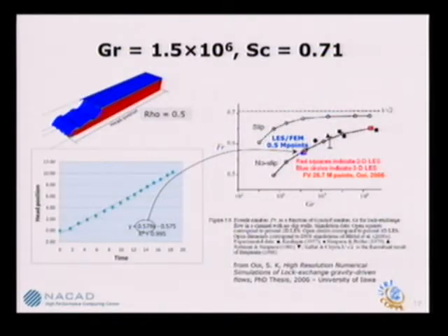And here, how we compare. This is the head position, which is one of the main targets of our study here. It's for no slip boundary condition. Our solution sits here. And the red square is 2D large eddy simulation, blue circles, 3D large eddy simulations.